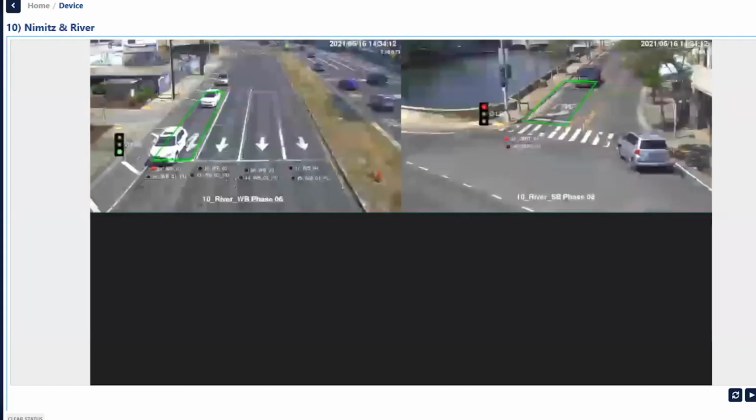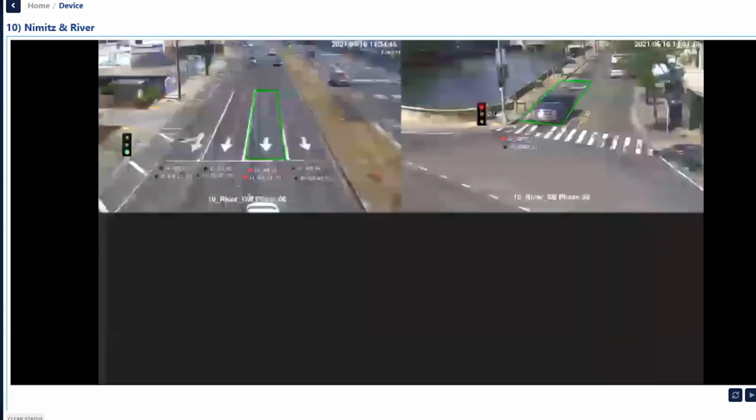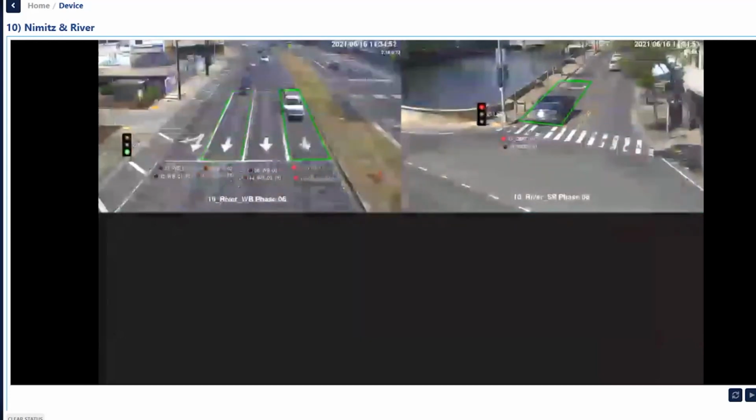So back to the question in the chat box, how we use the detection technology to detect the accident. Like I mentioned, we can use those sensors to detect the traffic condition change. So basically, if we know travel time become much longer or traffic density or occupancy level exceed a certain threshold, we know there's a bottleneck. So it must be something abnormal occurred. So, and then we can estimate where's the accident, what's the magnitude of the accident. So that's based on the loop sensor, for example.